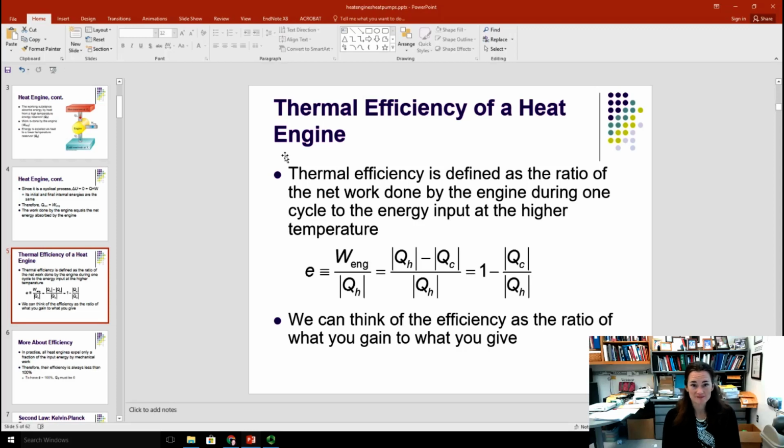that magnitude. All right? Now, since the work of the engine by energy conservation is equal to QH minus QC, then the efficiency also is equal to QH minus QC over QH. Simplifying that expression, you can write your efficiency as 1 minus QC over QH. So you can write your efficiency a couple of ways there, and it just depends upon what variables the problem gives you as to which one of the formulas is more useful.